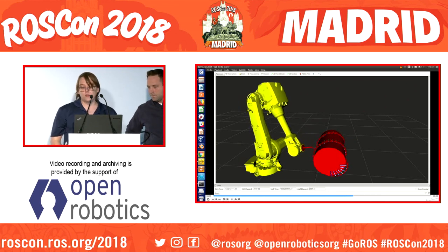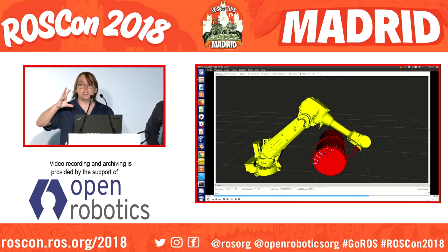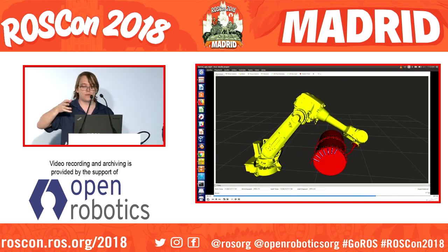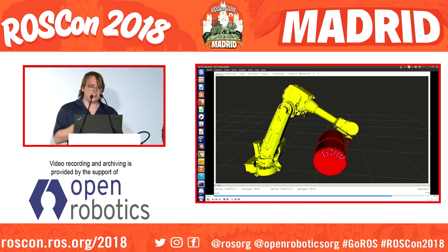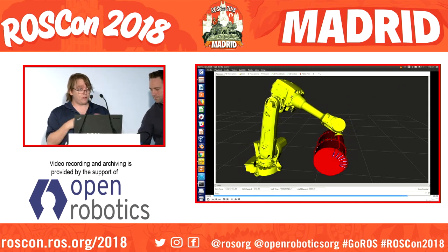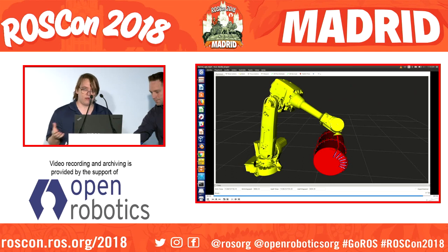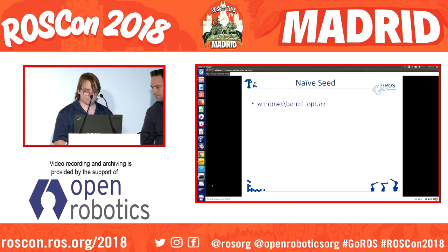And so what's the solution to this, right? Well, you could seed it. I could actually position the barrel at every time step so that this works. But what happens if your path is slightly different, or you have a problem that's hard to specify that seed? Or a lot of times what we do is we don't know what's in our environment ahead of time. How can we intelligently pick seeds or figure out what's going on? And that's where, if we switch back to the slides, that's where we use sampling planners.